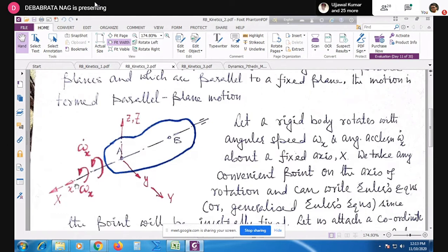So this will be the instantaneous axis orientation. At this instant, the body-fitted axes at point A share their orientations with the inertially fixed directions, capital X, capital Y, and capital Z. Now, the axes chosen in this fashion will, in the most general case, not coincide with the principal axes of inertia unless we have a special geometry of this body.